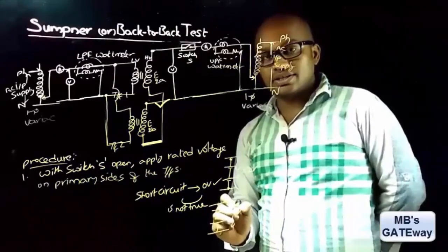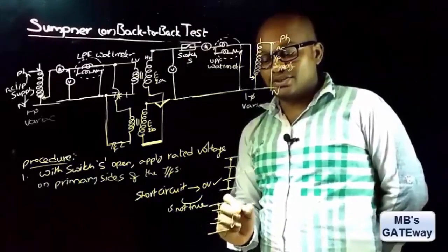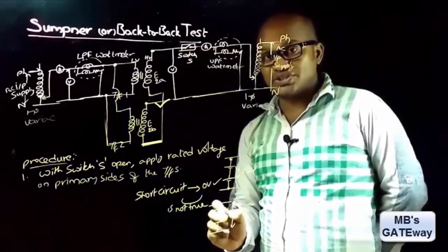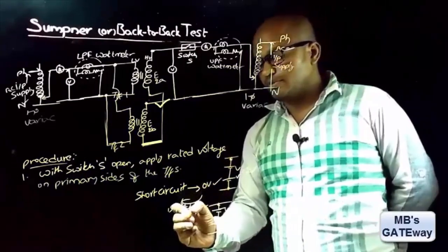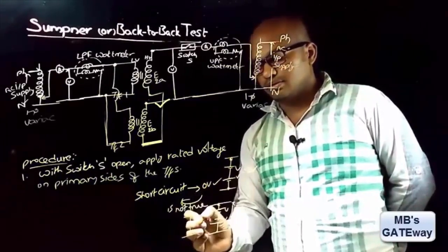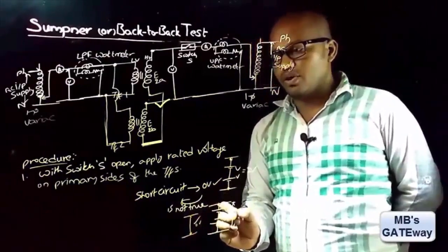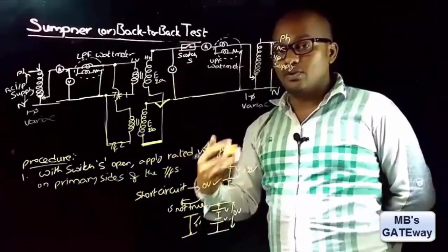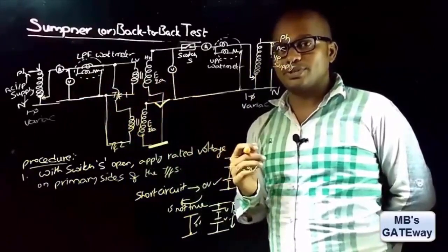And this 0 doesn't indicate that these two are short circuited, right? Here 0 means these two are connected in opposition and these two points are not short circuited. There is a lot of difference between the short circuit 0 voltage and this 0 voltage, and this is what is happening here. And now let's discuss, by viewing from this side, how this can be an open circuit test.